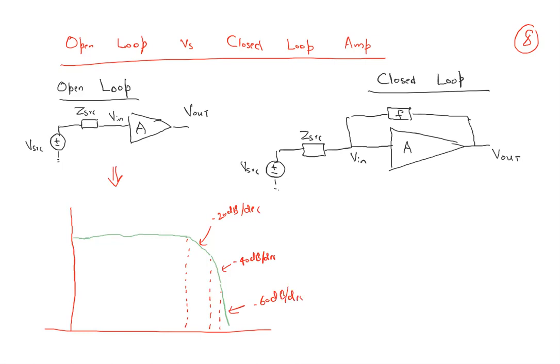The first point decides the bandwidth of an amplifier in open loop, so that is omega bandwidth. Then we have omega 1 and omega 2, and these are normally because of the parasitics. This is V out by V in magnitude. One thing you can see here is that all the poles are pretty near to each other.